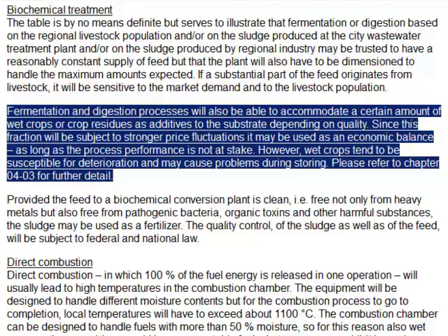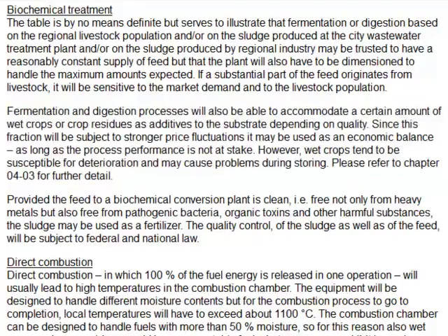As you remember from the resources lecture, since agricultural residues are seasonal, the digestion plant, or the fermentation plant for that matter, has to be able to accommodate the amounts of wet agricultural residues that may be produced during, let's say, June or July or August, during harvesting months, while at the same time it must be able to operate using only the constant flow of sludge or manure or whatever is available during the other months when harvest is not about.